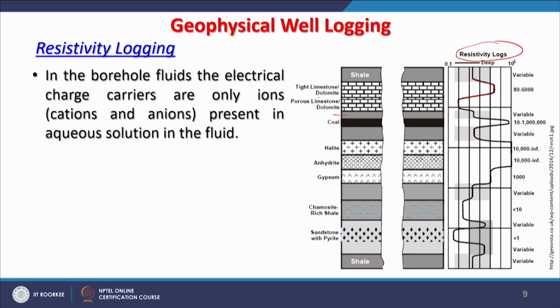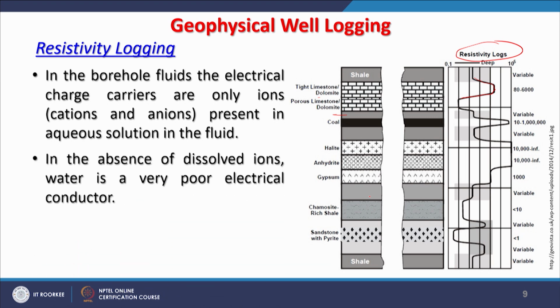Further, in the case of resistivity logs, wherever the water table or water level is present, that will also influence the log. The rocks may be of the same type, but if they are saturated in the top part and not saturated in the bottom part, then the resistivity will change immediately. So that will also indicate where the water level has come.